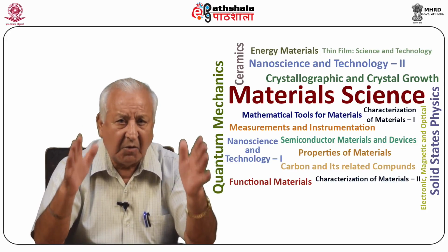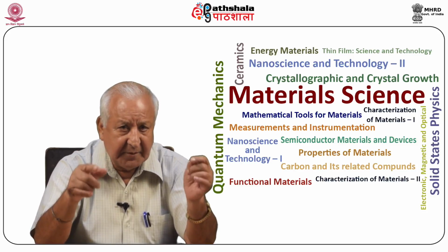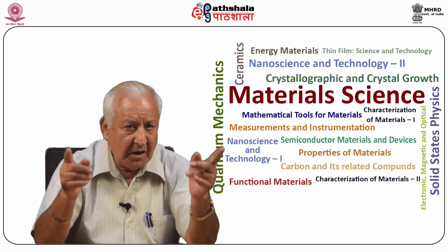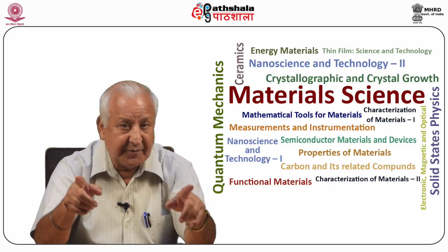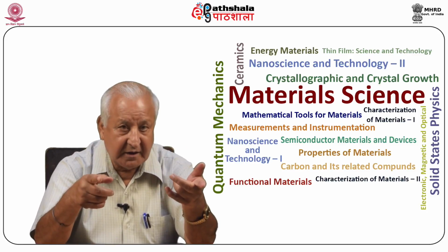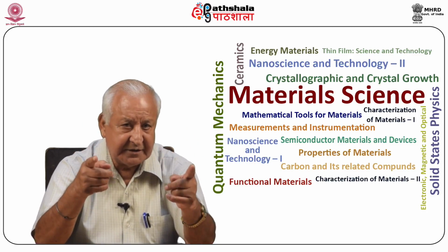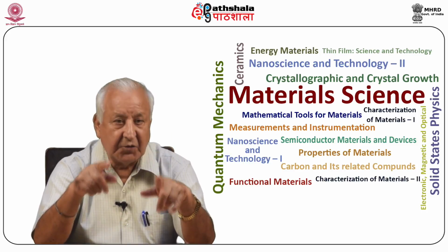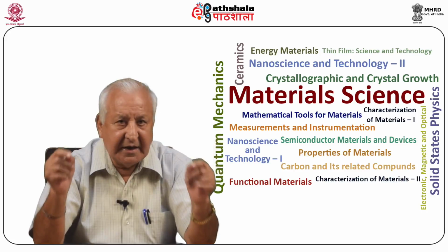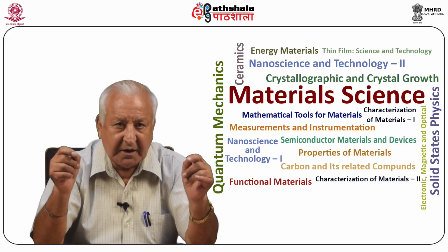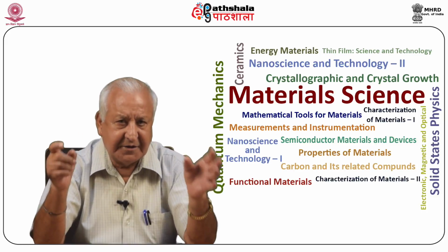Most of the mechanical properties of crystals, including elastic moduli, slip and plastic deformation, hardening by alloying and heat treatment, annealing properties, and work hardening, can be explained in terms of the motion of dislocations and the interaction of dislocations with one another and with impurity atoms. Any detailed discussion on this topic is beyond the scope of this lecture.